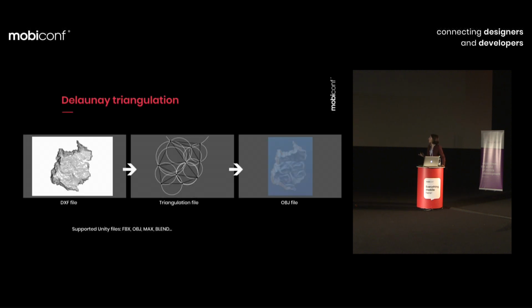Well, this goes deeply into mathematics, but without entering too much into detail, there is a particular algorithm called the Delaunay triangulation. That is a particular way, let's say, to join a set of points to make a triangular mesh. Delaunay triangulations tend to avoid producing skinny triangles, and this is very suitable for terrains.